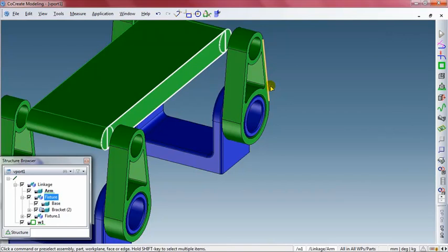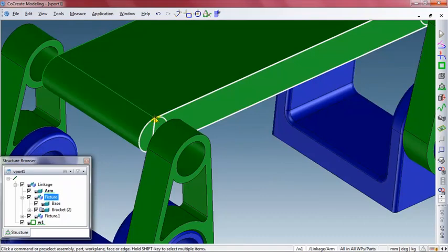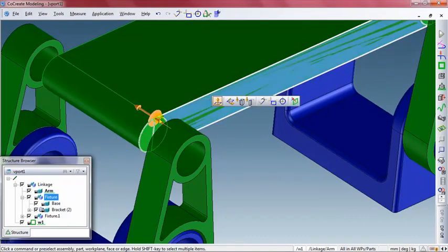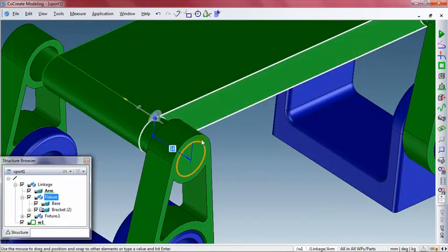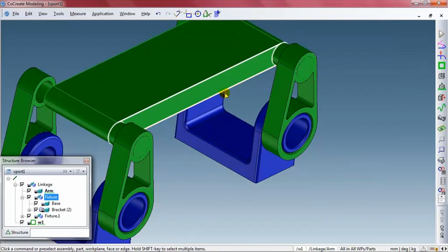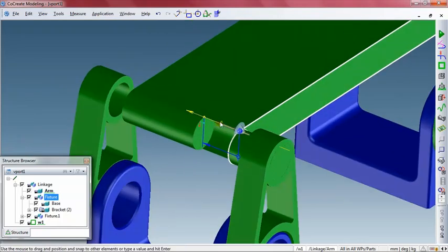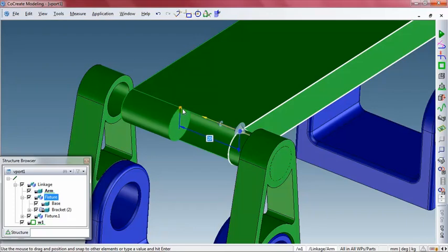I can bring back my profile to reuse some of the existing 2D data. Here, I only want the 2 circular profiles to be pulled to the width of the brackets. I'll reuse that profile one more time to create the cylindrical shafts on the far side of the control arm. As you can see, the pull command is automatically removing material because the profile is cutting through the part. We can easily change this to add material.